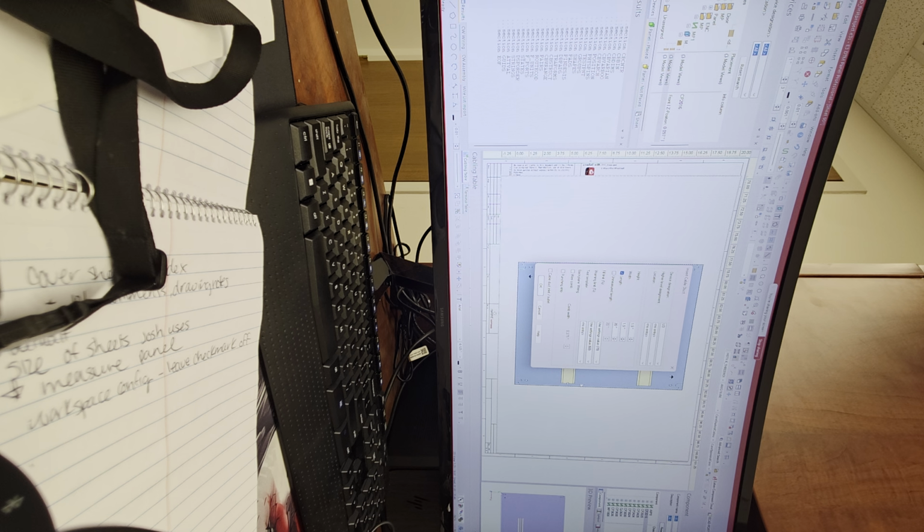So in this case, let's just make the length, I don't know, let's just say 8 inches or so to make sure it fits both on the plane. It's slightly longer than the thin rail itself. And the text template, this is the option where you can choose in that drop-down menu what kind of text marker, text type, and what kind of text do you want to show on your duct itself. So as a baseline, select text C. It's the one that has the most basic info on it. Once you place it, I'll show what that is. Yes, this is all good. Click OK and place it.